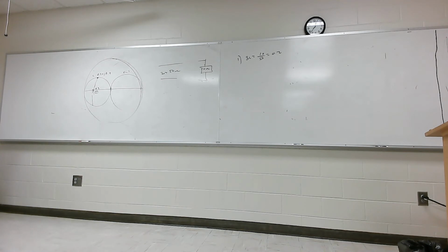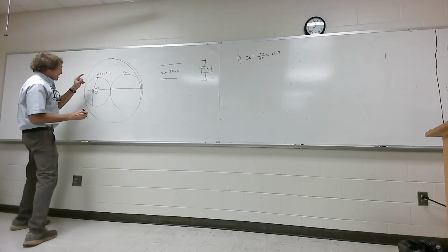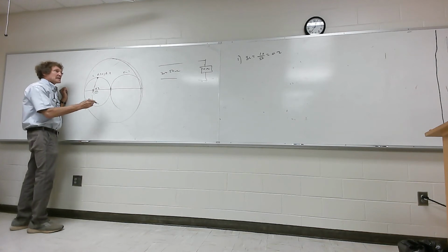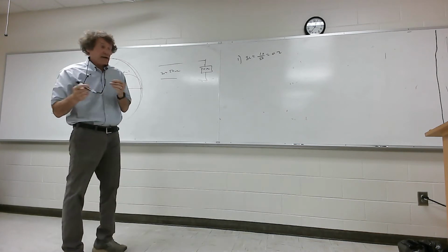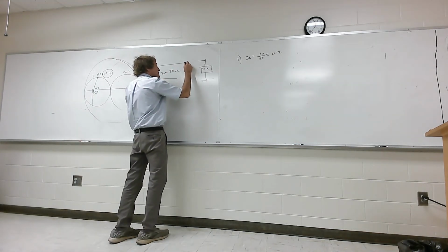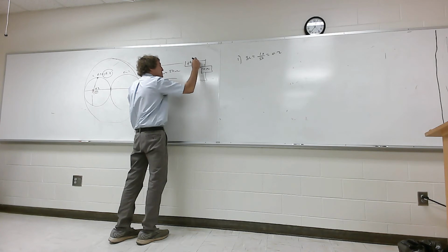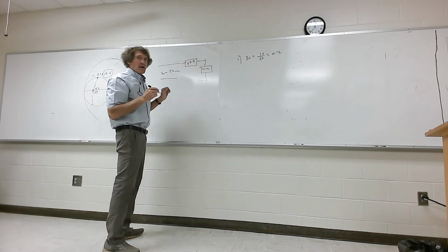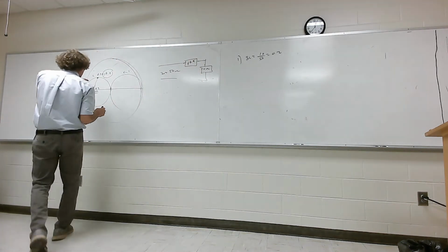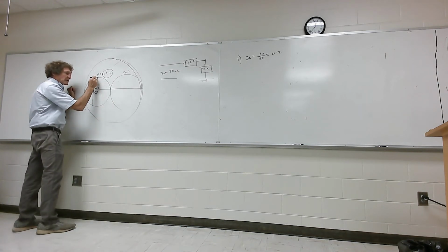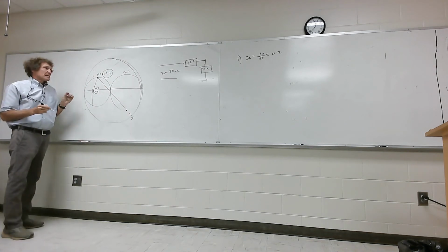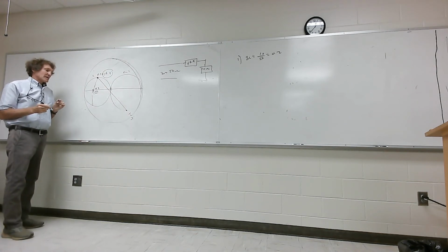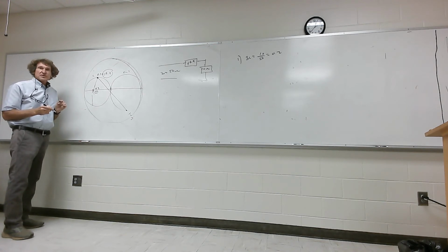So if you look at this, that means I added what? I added J0.4 here, correct? You had J0, I added J0.4, this is in series, so it's a series element and it's an inductor. Now I'm right there. Now take 1 over that, and I better be at 1 minus J something. Oh boy, almost afraid of this. Just take 1 over 0.2 plus J0.4.